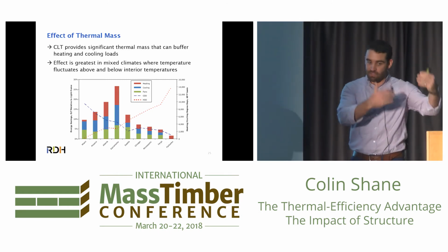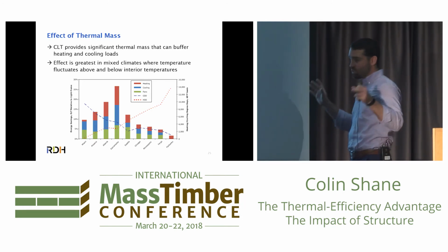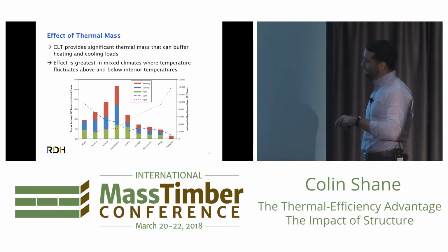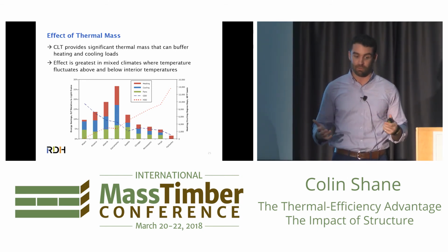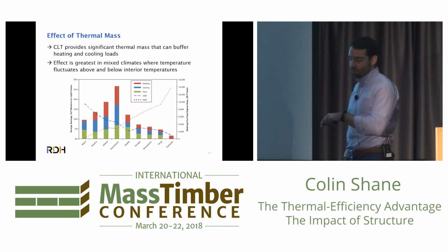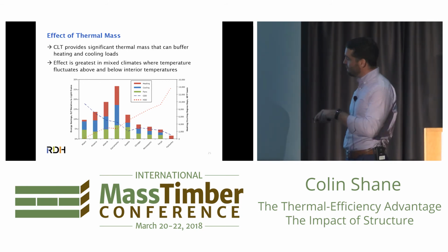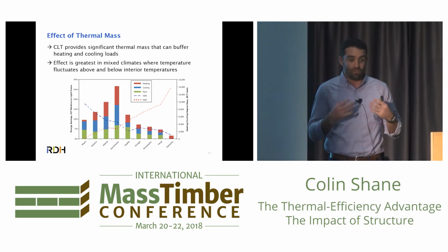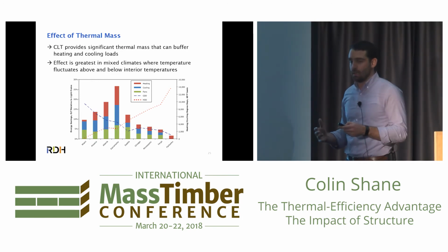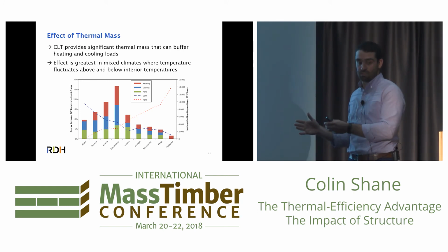But when we're talking exterior insulated assemblies in comparable type assemblies, just altering the structural material, we're talking in the range in many climates of somewhere from 5 to 20+% energy savings overall just because of thermal mass and no other difference. So again, there's lots of research and lots of background about this in the CLT guideline for those that are interested. But again, combine the thermal mass effects with all these details that just become naturally simpler to do better thermally with mass timber, the thermal performance of these buildings is much further ahead than it would otherwise be with some other structural materials.